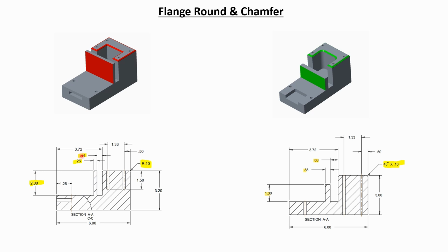The space, which is 0.44, the slot here, this space will not accommodate a larger diameter tool that has the 2-inch reach. So realize that these features can be attained using a wire EDM. But that now introduces multiple setups, which in turn introduce new complexities and add up to the cost of your part.